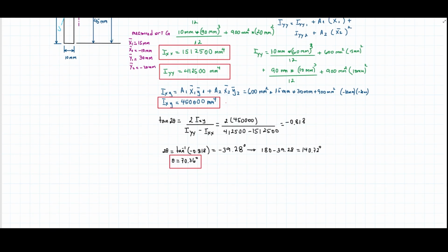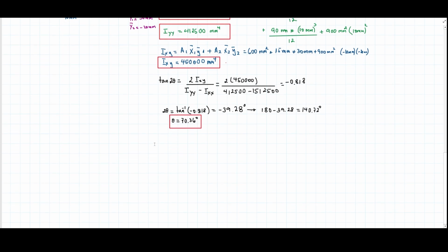And to do that, we need to rely on the similitude between the definition of the principal axis and the principal stresses, something that we took a look at in the lectures. By bringing that formula where we were using Mohr circle to calculate that, we're not going to use Mohr circle, we're just going to use the formula here. So the moment of inertia around the first principal inertia axis is, again by similitude with the principal stresses formula, going to be equal to this one here, plus the moment of inertia about y, divided by 2. Then we're going to have the subtraction of these two terms, minus this one here, divided by 2, multiplied by the secant of the double angle. So we already know the double angle, and let's apply the formula.